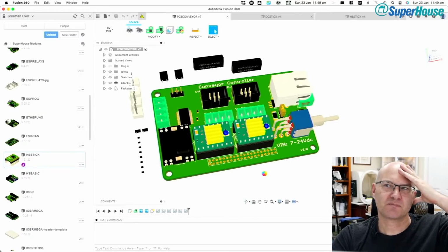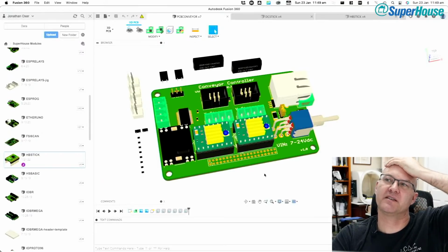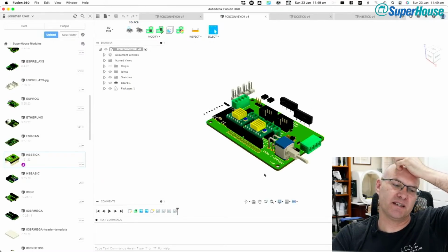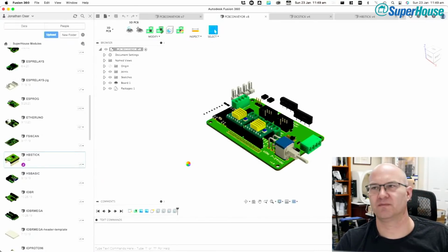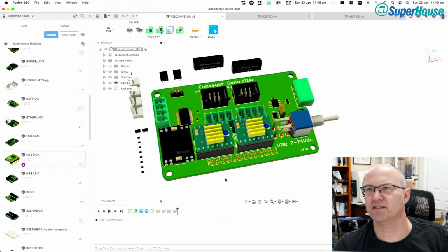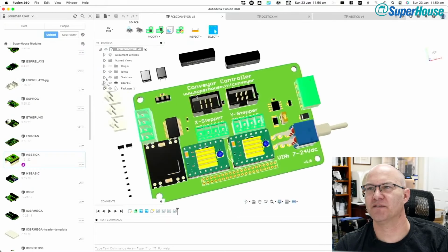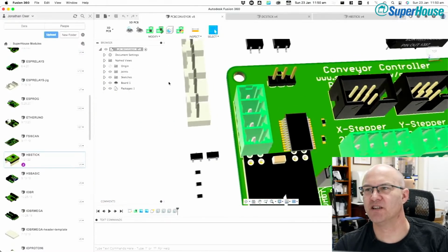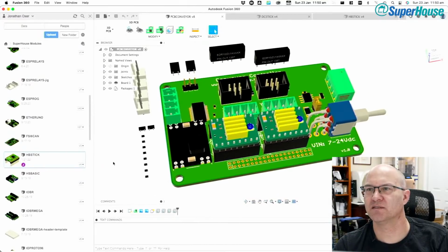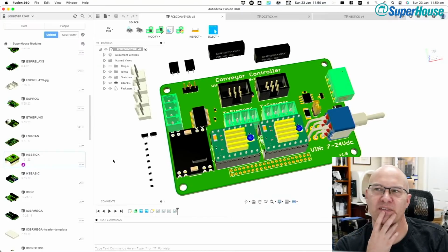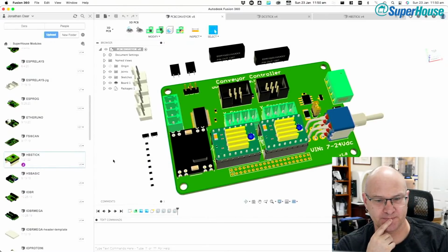So for my use case, I could get away without them. And another way to do this would be to, instead of using opto-isolators, just use transistors. Like I could just put a little N MOSFET or something in there and feed that through from the external thing. So instead of having this big package here, I could have a little SOT23 package. It just wouldn't give the same really high level of isolation as an opto-isolator.